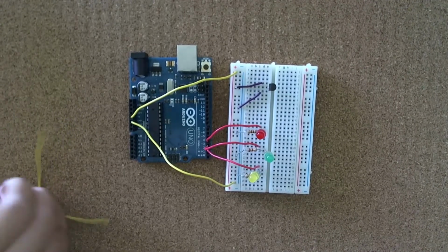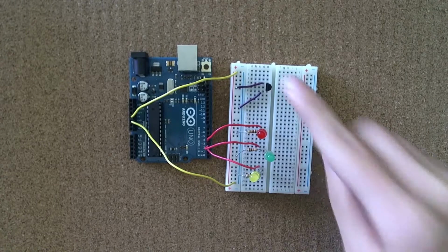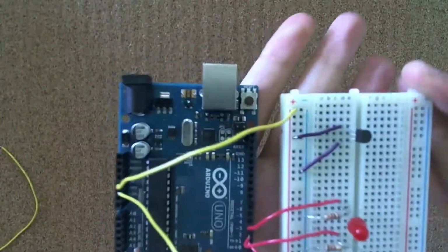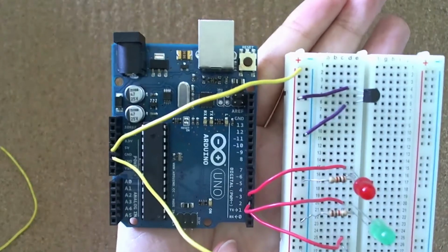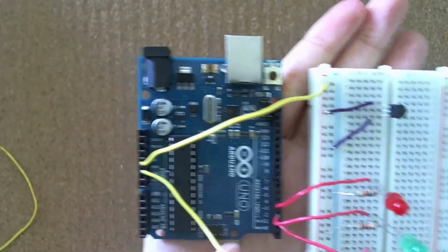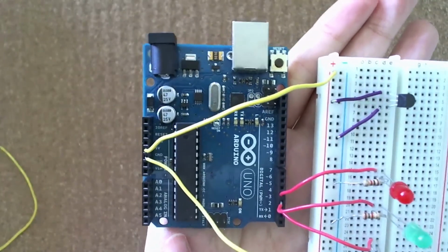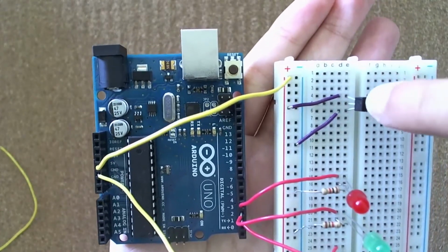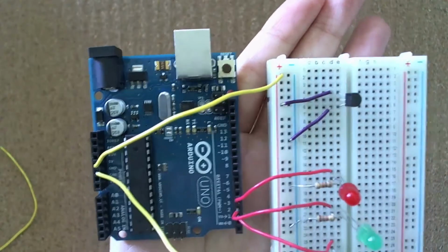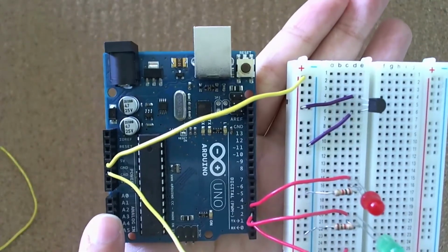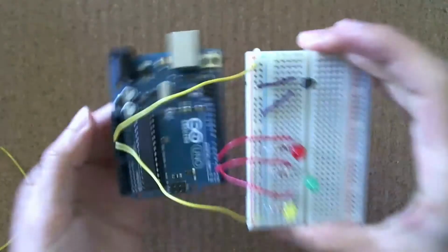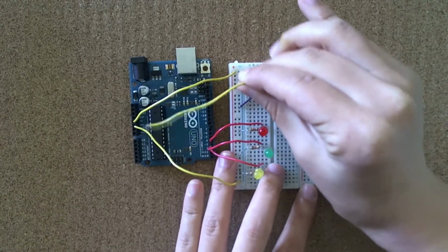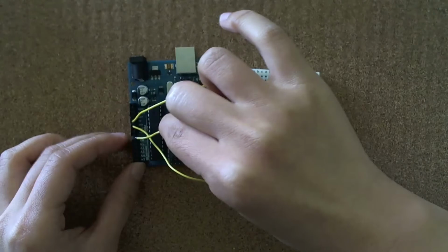In this middle section, you want to connect with an analog pin. We want to read the signal from this. If you look at your Arduino board closely, you can see that on the right side it says digital, and on the left side it says analog. So we want to read the values sent from this middle pin of the temperature sensor to A0 over here. So I'm going to connect a wire from the middle all the way to A0.